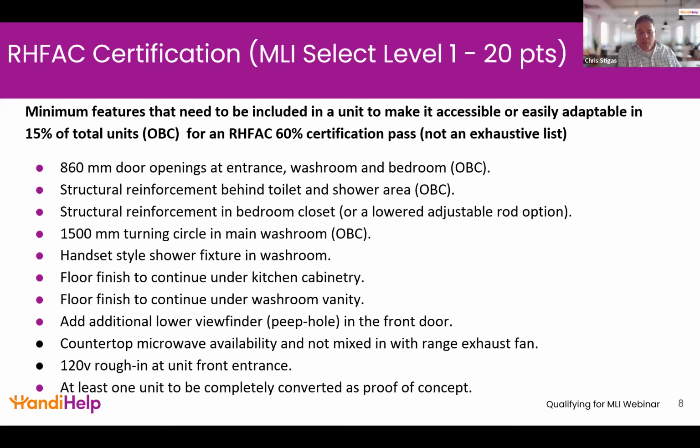I'll touch on the flooring finish continuing underneath the kitchen cabinetry, for those people that are new or just to refresh. The reason that the flooring finish needs to continue underneath the kitchen cabinetry is that it's one of the things that makes the unit adaptable. The idea is that you can use conventional kitchen cabinetry in your barrier-free unit. And if and when the time comes for somebody that has accessibility needs, they'll be able to remove the doors of the kitchen cabinet.